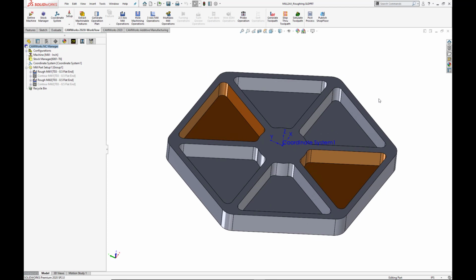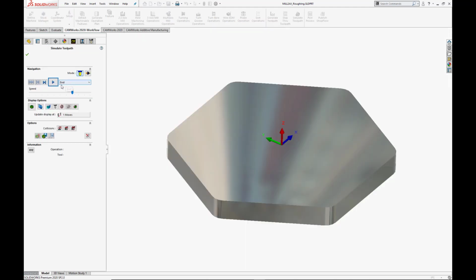2.5 axis volume mill versus traditional roughing. High-speed machining, high-volume machining, high-efficiency machining. You probably have heard of these fancy terms at one time or another, and what it basically means is removing the maximum amount of material quickly while maximizing tool usage and lifespan.